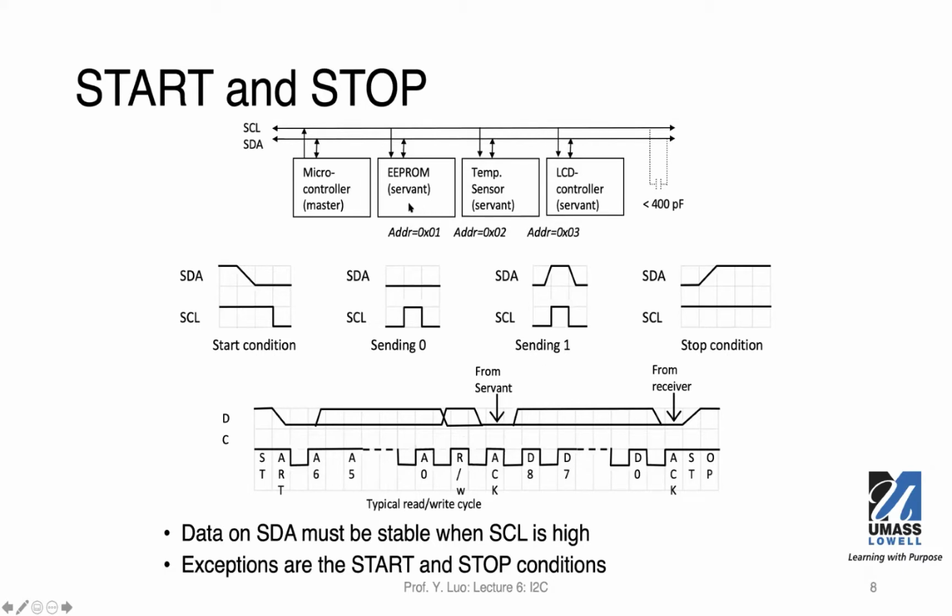But is a servant always a receiver, or is a servant always a sender? The answer is no. Because when we say sender and receiver, we're talking from the data transfer perspective, where the data goes from where to where. We say that the data goes from the sender to the receiver. So if we're reading, let's say the microcontroller reads from EEPROM, who is the sender in this case?